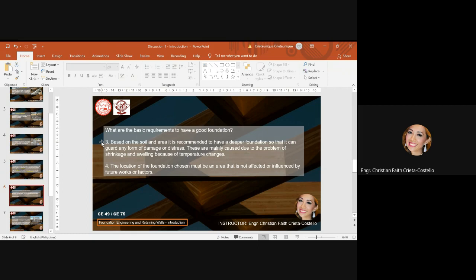This is to know and to consider together with your design the quality of soil that you are working with. And it is very important because if you do not know the quality of soil that you are working with in your design, then even if you're a good designer, but the soil will not be compatible to your expectations, then your design will basically fail. So soil testing is really a must, especially if you are doing a high-rise building.